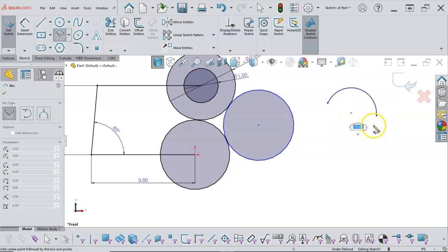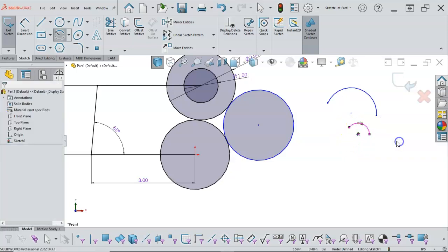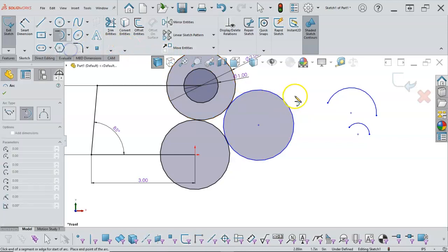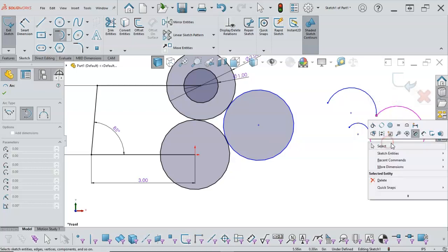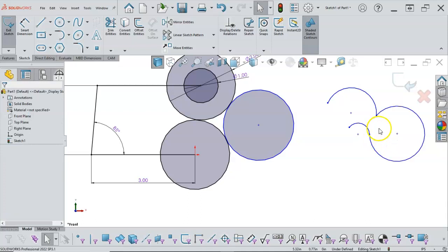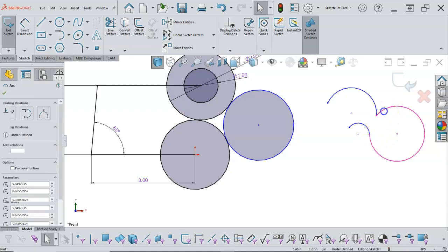We click a point, drag approximately through the arc. And the thing to keep in mind is if it goes the wrong way, which occasionally you will start to drag and it will jump the other way, drag back to the beginning and continue on with the arc. Our tangent arc requires that something be in existence, and whatever endpoint you click, you're going to be able to drag off of that object.